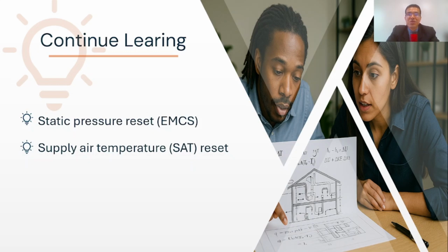You should explore the idea of supply air temperature reset. This concept is used to cut coil cooling and reheat when loads decrease while still meeting indoor quality and comfort constraints. You could read about the airside economizer. This concept is used to increase outdoor air intake under favorable ambient conditions to lessen mechanical cooling, with attention to humidity limits and minimum outdoor air requirements.